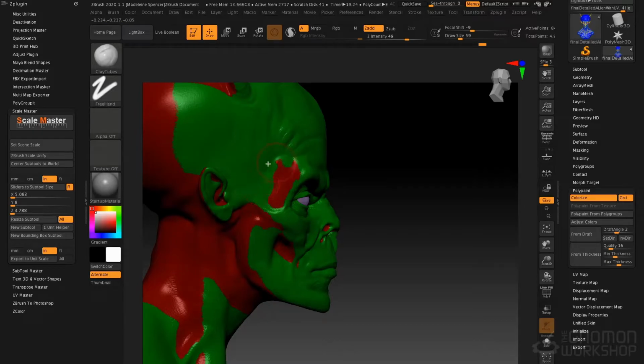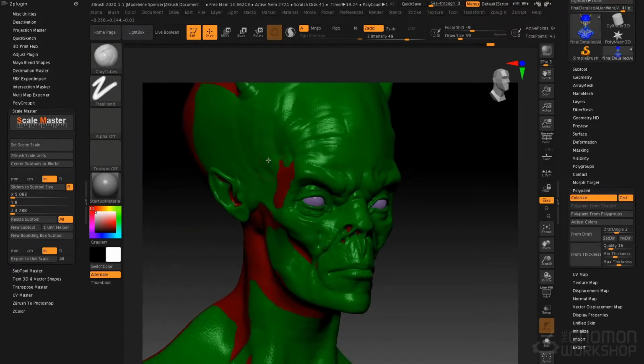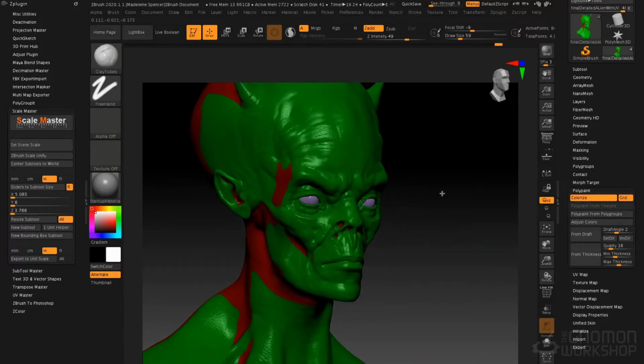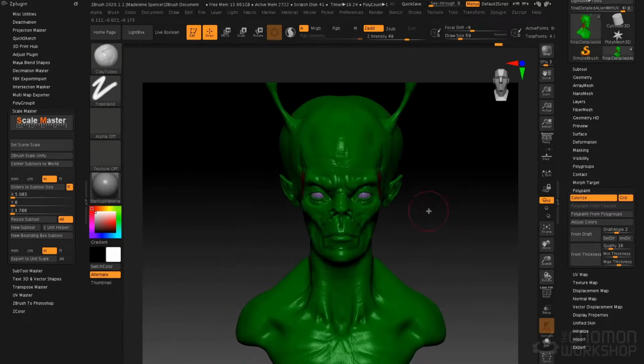Now, this is really only something that you need to be concerned with if you're creating an object that's going to be a solid that's being pulled from a solid mold. Flexible molds like silicone molds and urethane molds, that's not as much of an issue. But anytime we're doing injection molded plastic, knowing your draft angles is very, very important. So this is extremely useful for those people that are interested in that type of manufacturing.